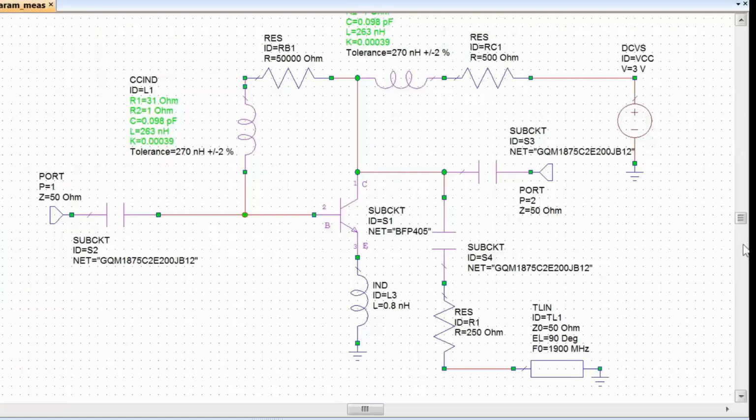In our previous tutorials, we looked at how to characterize an RF transistor through its IV curves and how to design a bias network which would fulfill specific design requirements. We also made sure, by using DC blocking capacitors, that no DC current would flow out of a bias network into our RF source and our RF load. This would have loaded our bias network and therefore it would have affected the bias.